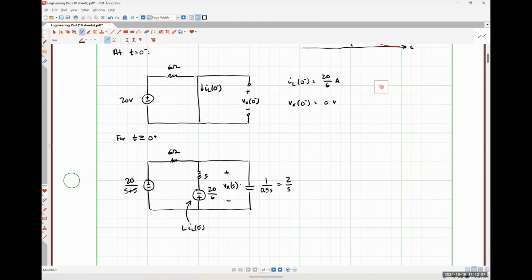And so we would simply analyze this circuit by whatever methodology seems appropriate. If I were doing this, I would probably do nodal analysis, just because my only unknown voltage, if I choose the bottom terminal as ground, is the Vx that I'm looking for. So this is circuit analysis. You guys know how to do that fine.